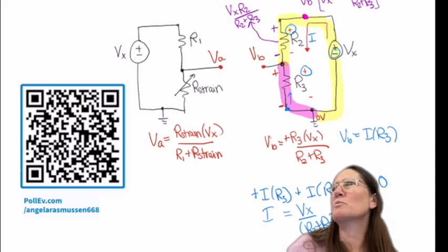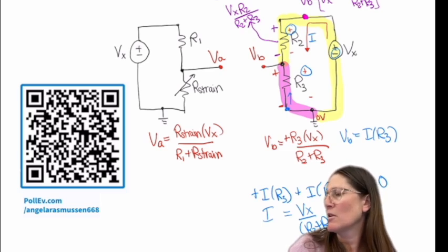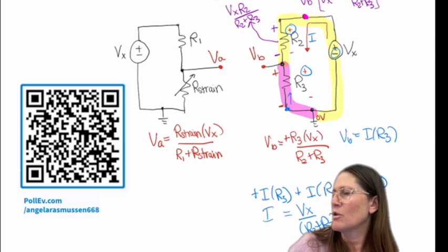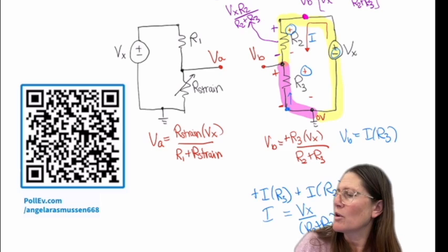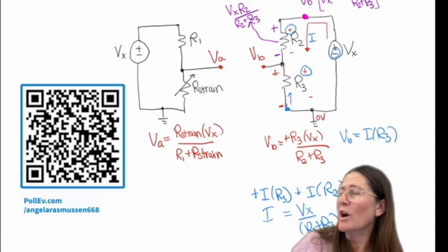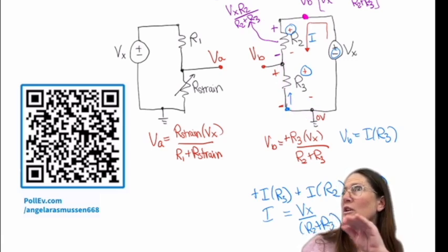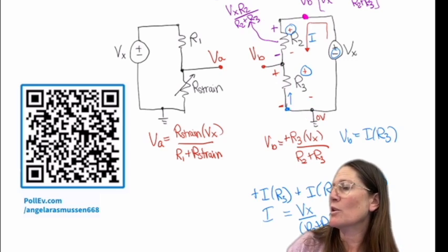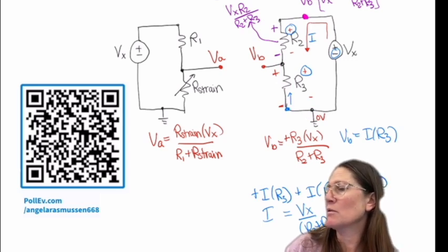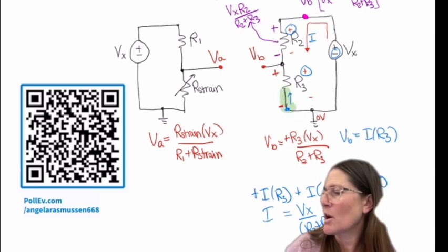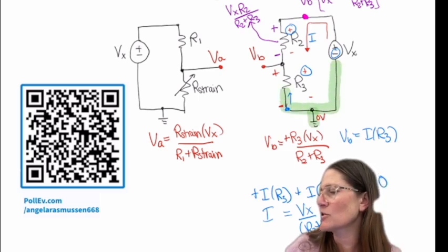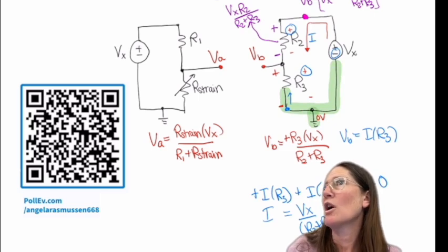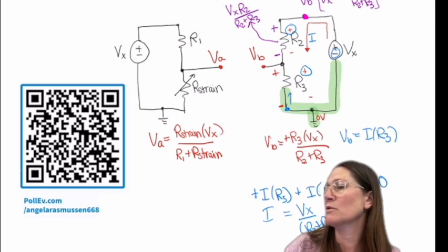Isn't the 0 volt reference, purple to the negative side of the battery, the same node essentially? So the node itself is 0. I was just drawing and highlighting the pathways there. But the node itself goes up to an element, so all of this is your node location. Anywhere I measure on that node is going to be 0 volts.